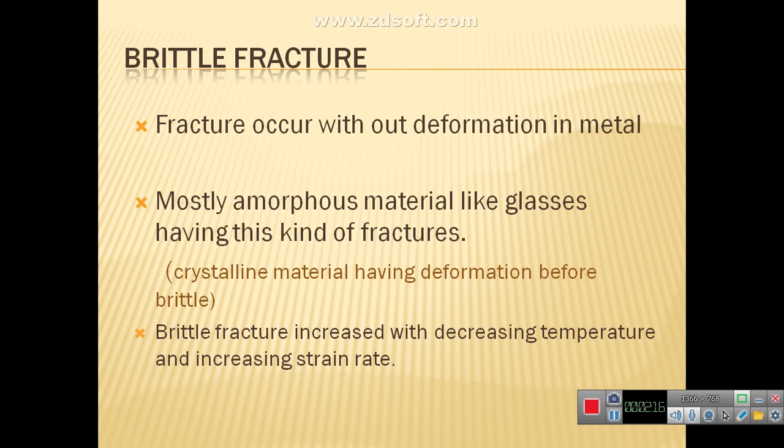Next, we move on to the brittle fracture. Brittle fracture occurs suddenly and catastrophically without any warning. Fracture occurs without any deformation. Most amorphous materials like glass have this kind of fracture. Crystalline materials show some deformation before brittle fracture.